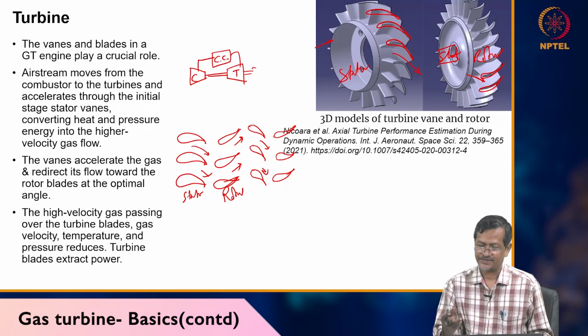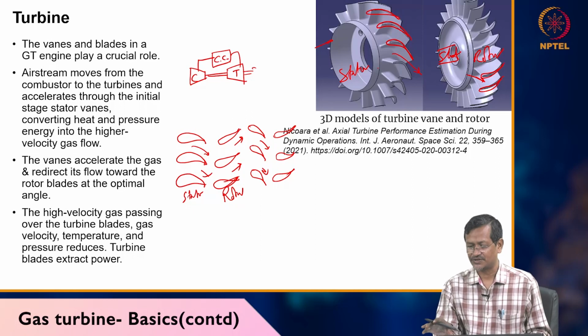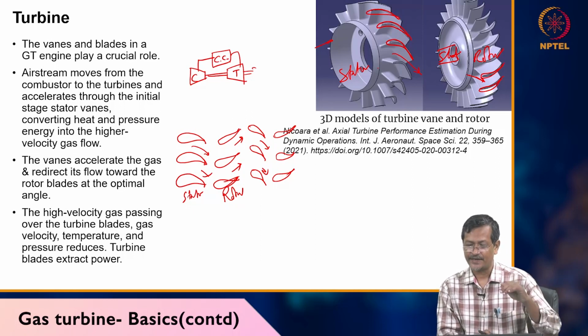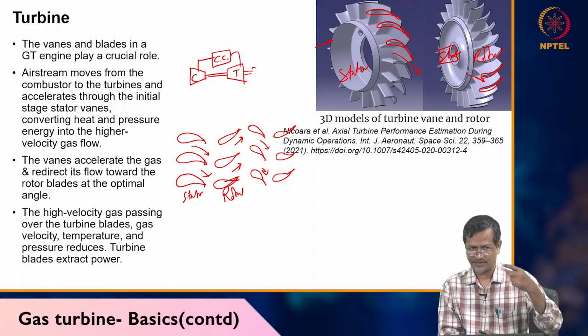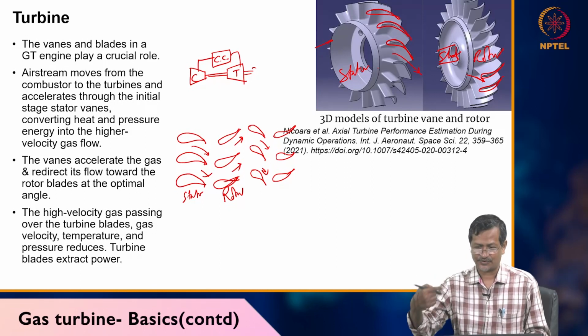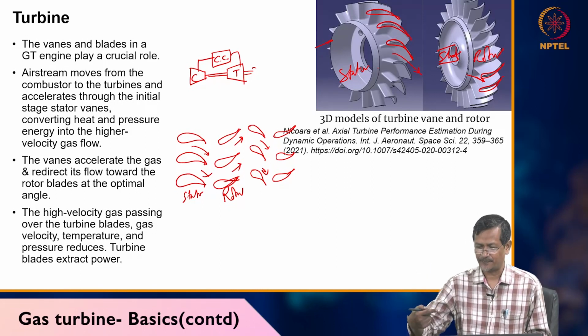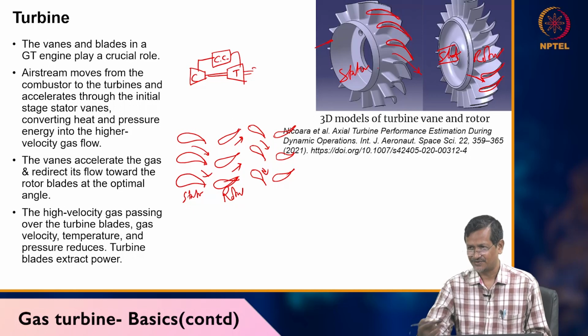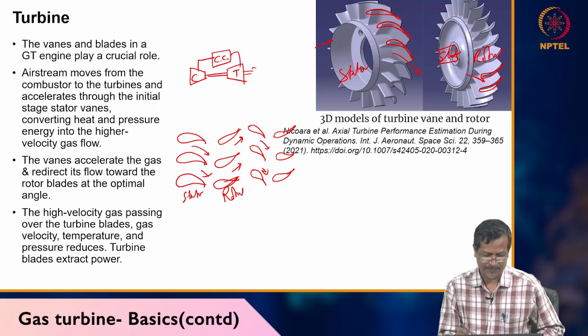Okay, and it will be facing very high temperature. So material consideration is very important for the turbine rotor, especially the rotor blade, because the stator is not rotating. Because of centrifugal force, something can happen; the chance is less for the stator, but the rotor is rotating, so there is centrifugal force and vibration, plus high temperature. So material creep is one important parameter, creep.